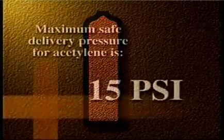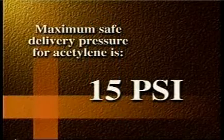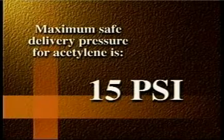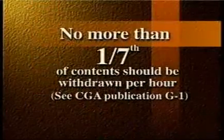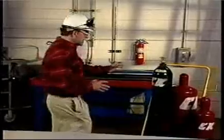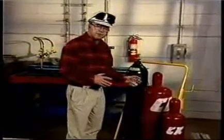Under industrial guidelines, the maximum safe delivery pressure for acetylene is 15 psi. To minimize the chance of withdrawing acetone from the acetylene cylinder, no more than 1/7 of the contents should be withdrawn per hour. This acetylene cylinder contains approximately 300 cubic feet of gas.